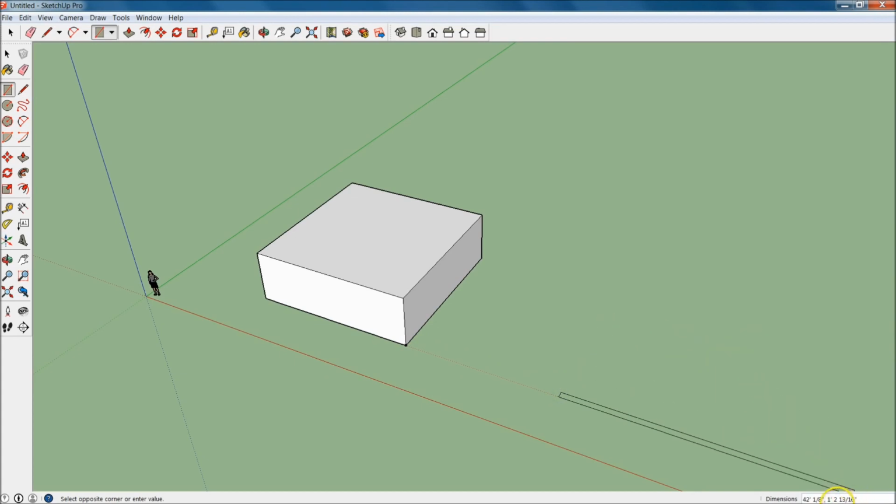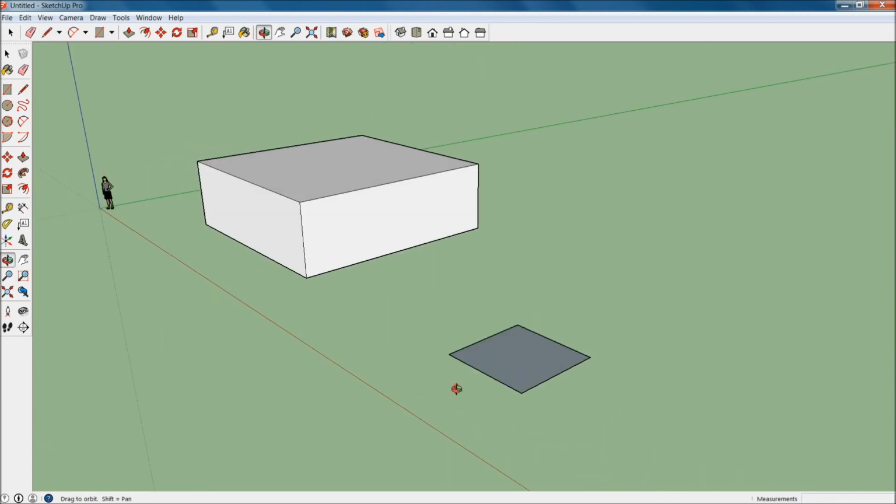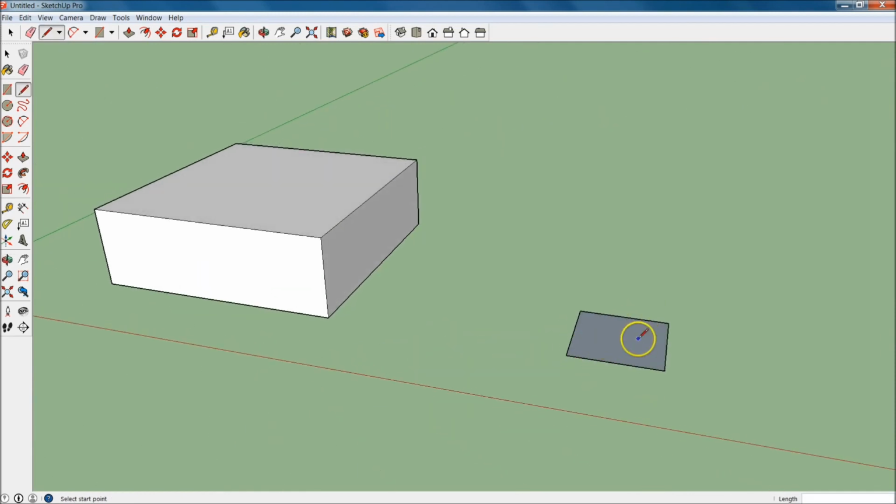And you'll see that these dimensions, how they're formatted, are a little bit different. Let's go ahead and pull this out, and we're going to make a 10 by 10 shed. How this is formatted is it'll take your X and then it'll take your Y dimension. You'll see that there's that comma right there in between the two. So what we're going to write is 10 feet, comma, 10 feet, and hit enter. And you'll see that it's 10 by 10. Double check it. 10 by 10.